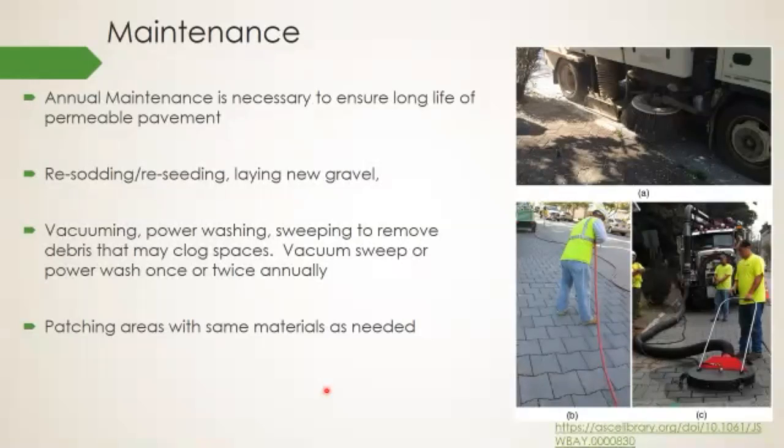Now for the permeable pavers and even for the pervious concrete and pervious asphalt, we'll need to do power washing, where we're cleaning out the sediment, as you can see here. This gentleman is power washing out these nooks and spaces to clean out things like moss that can grow in there, soil sediments, any kind of junk that can accumulate in there and basically turn it into an impervious pavement system where water isn't able to infiltrate.